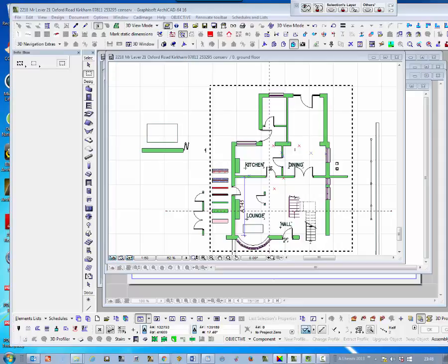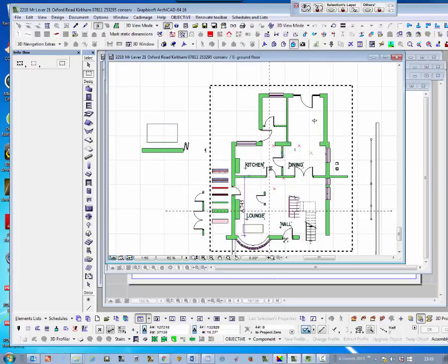Generally, the upstairs, the first floor level would be pretty much the same, so we'll change that again, 2520. And before we come out of this, we'll actually highlight the ground floor again and press OK. If we don't do that, we'll end up on the first floor on the plan itself. Now that's changed the story heights within the model to that dimension, 2520.